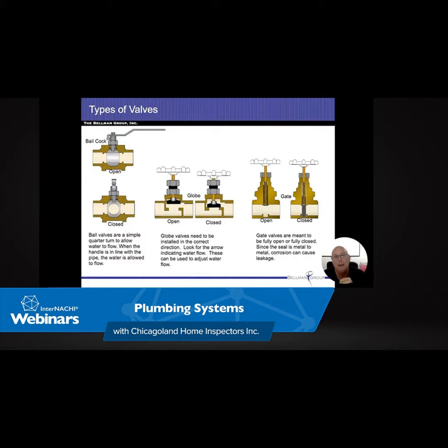And anytime I see them in parallel, I do check and make sure that the distance between A and B as shown on these diagrams is identical. And the same thing for the hot water side. And both water heaters have to be identical. I'm talking not just the same manufacturer, same year, same size, same height. We can't do anything that's going to change the flow.